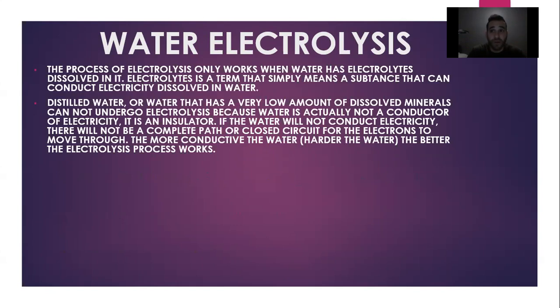Now that I have a mineral water, which a lot of our source tap waters and well waters around the world, the majority of them, are going to have a sufficient amount of minerals, this process can take place in the device. So the harder the water, which means the more minerals, the better this process actually works because the water is more conductive. So you have a higher conductivity of water, and the process can work more effectively.